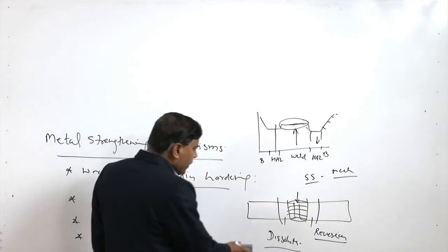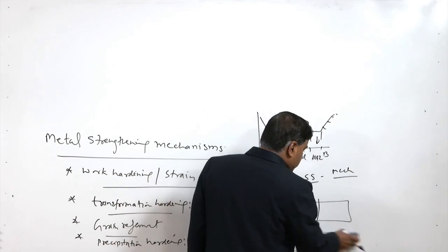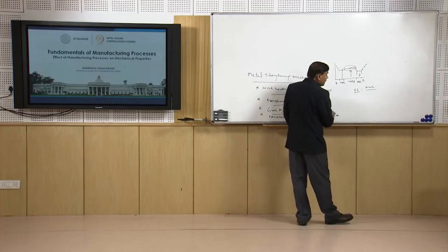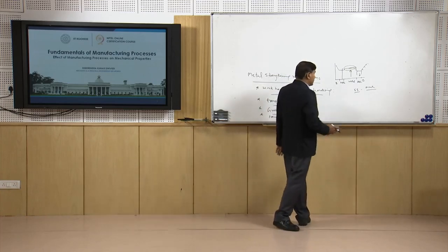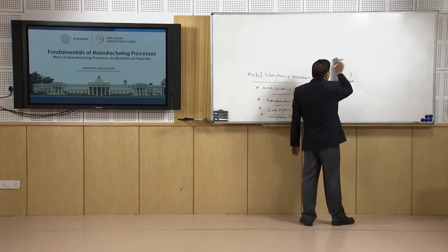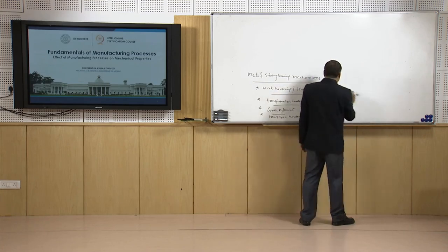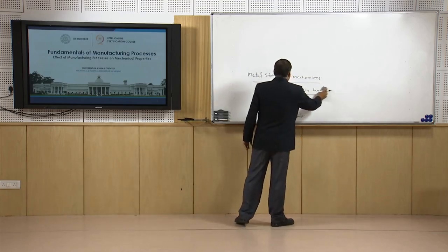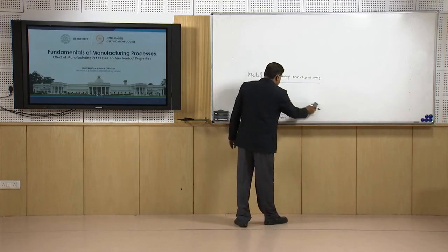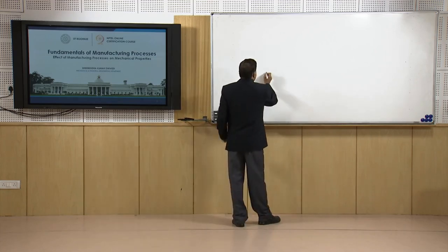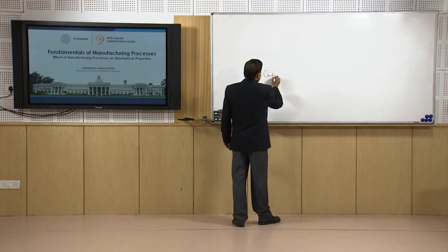So, wherever there is a rise in temperature during the manufacturing of these precipitation strengthened systems, there will be a change in mechanical properties, depending upon the extent to which these precipitates get dissolved under the influence of heat. Now, coming to the specific casting processes and the factors that govern the mechanical properties. So, here, casting.